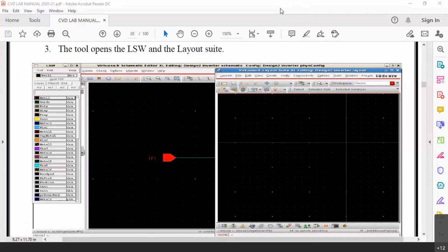So let me proceed. You can see at the right side, there is this particular window which has 4 quadrants. This is nothing but a graph sheet. In the graph sheet, in general, we will make the layout always in the first quadrant, unless otherwise specified for other things. In our lab class, we always use the first quadrant. The reason is, once you make a layout, ultimately that layout has to be converted into a file called GDS2.